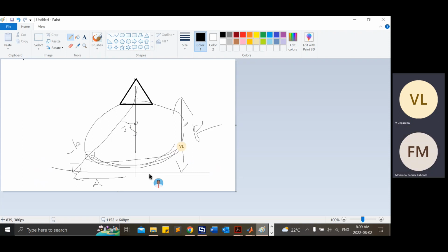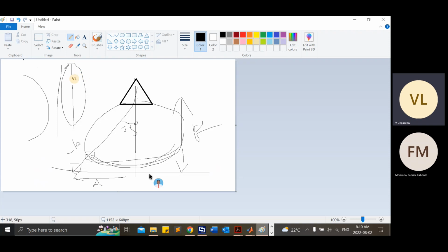Ideally, what we have to do is give a parabolic distribution. The reflector is a planar parabola, and that will add phase to it. If you excite a plane wave and you have designed the reflector as a parabola, it will give a parabolic shape only, and the phase values will be in accordance.